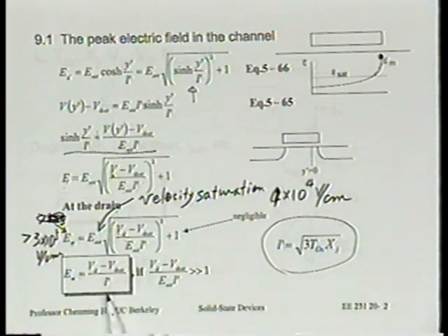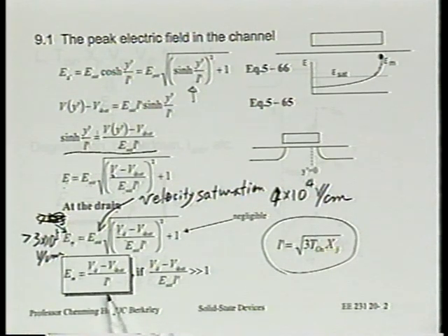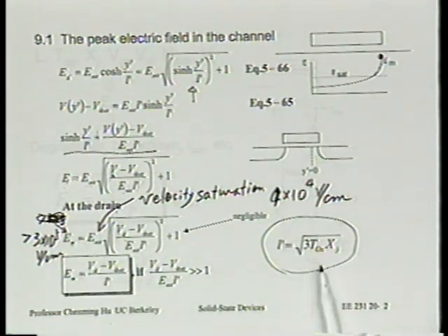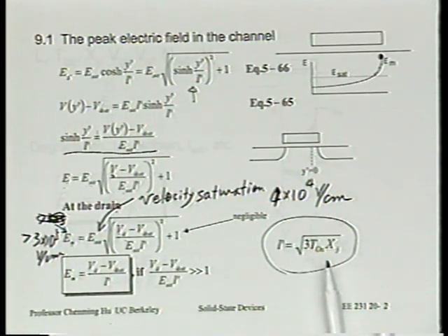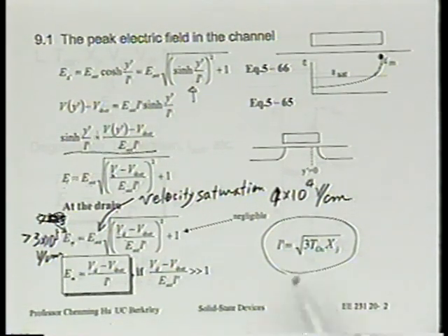Now let's look at here. If your concern is high field effect, meaning you're trying to control the electric field, don't let that get too high, then do we want L prime to be large or small? Yeah. So this is a fundamental problem between the performance of the transistor and the reliability of the transistor. So when we scale the transistor, we're going to have more reliability concerns. Certainly this is a problem, right? We know that we want Tox to be small for many reasons, not just channel length modulation, short channel effect, we have seen that, and certainly ID sat, we want that. But when we do that, then the electric field becomes large. Is that right? Okay, for any given VD minus VD sat.